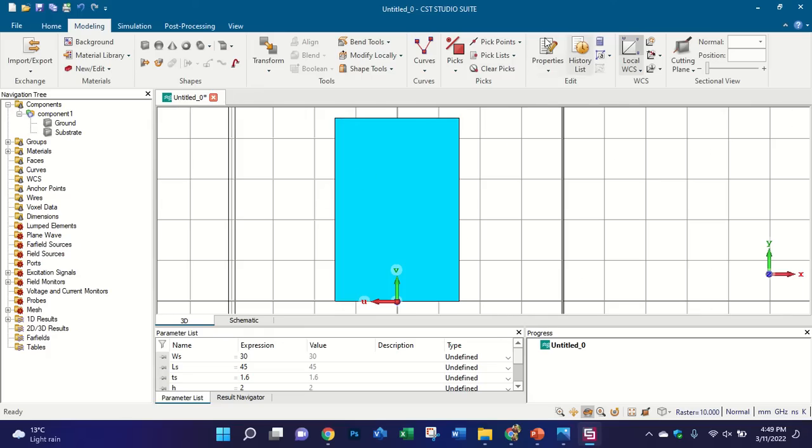Now we design a patch. In a reconfigurable antenna you are more open than with simple, previous antennas like the patch antenna and other antennas. You can add PIN diodes wherever you want, and you need to check if it is working well, then you can claim your antenna as a reconfigurable antenna. But if it does not work very well, then you only need to change the position of the diodes.